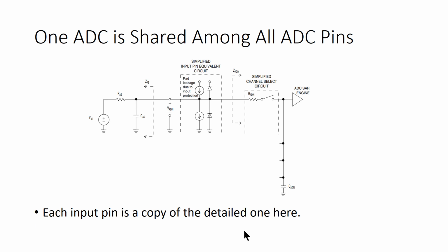The measurement circuit has a charming alphabet soup of vocabulary indicating what it is. The ADC SAR engine is short for Analog to Digital Converter Successive Approximation Register, which is just a fancy way of saying that it measures a voltage on this node. We can cover that up too, and just remember that we're measuring the voltage at the node labeled V measured. That leaves us with a less complicated diagram, and we can actually break it down even further by noticing that there are three parts to this diagram.